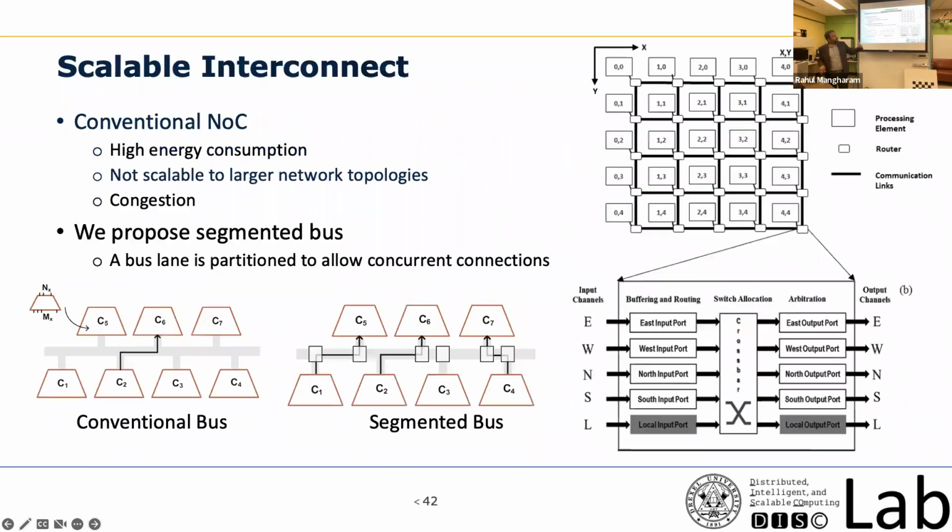And in the next few slides, we have modified a lot. For example, we have moved away from the conventional network on chip, because in a conventional network on chip, each router has a lot of storage. Every packet that comes in, you store it in a buffer and then forward it to another port. Each router can have east, west, north, south directions, so whenever a packet comes in, you route it east, west, north or south, depending on where your destination is. So you have to have all that information stored in the router to know where to send it.